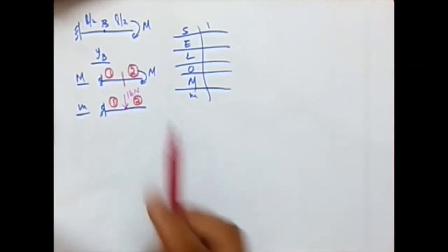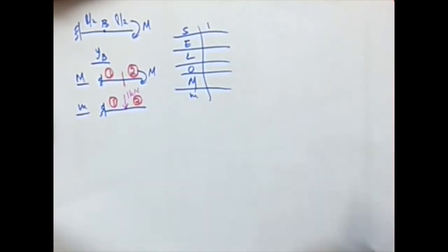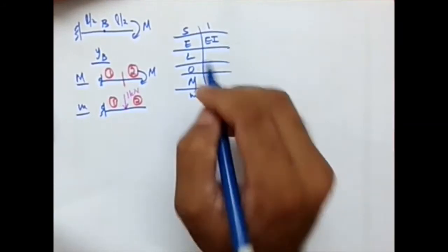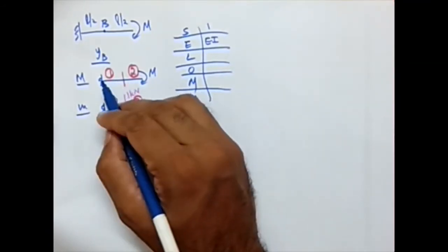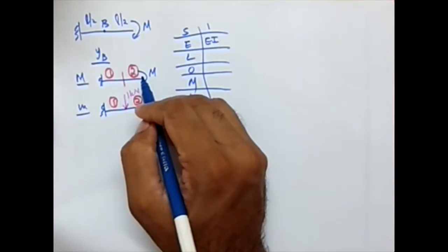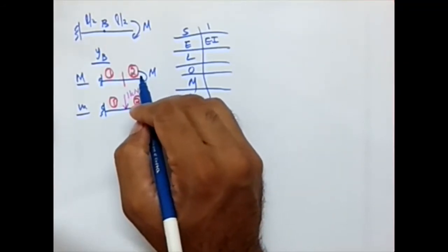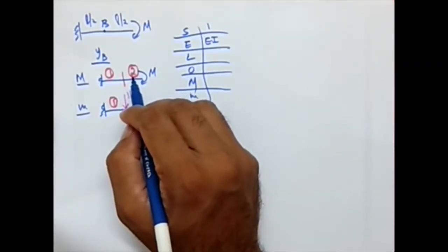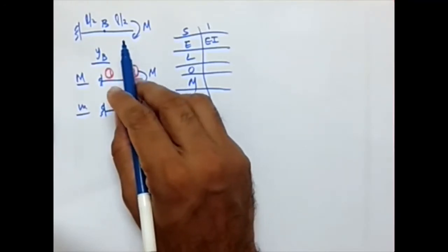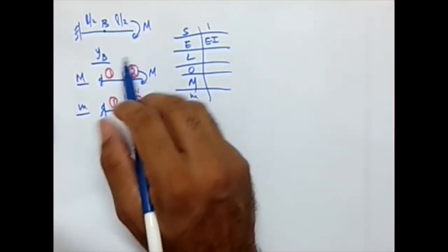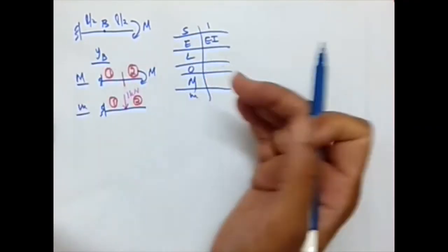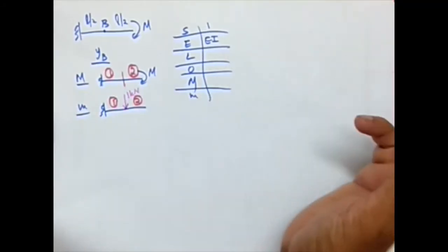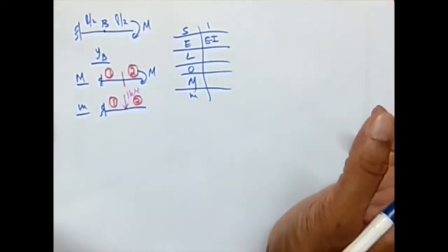Okay. And the EI value, it is constant. Limit is what we need to think about. So I can consider either this as the origin, this as origin, this as origin, or this as origin. Whichever I'm taking, it is fine. But whenever we are dealing with cantilever, I will always recommend you to look for the free end as the origin. So all the free end should be on the free end side. Better avoid it from the fixed end side. So B or C, whichever you prefer, you can take it as the origin.